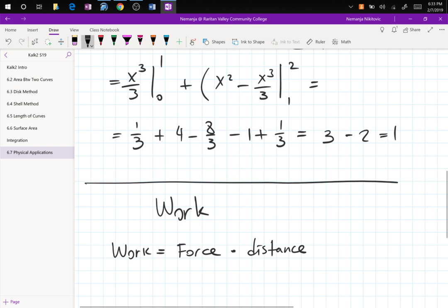So this desk is not, I mean, I'm infinitely strong, so for me it's nothing, but if you try, right? You push this way, you will start ripping the carpet. Because you are leaning onto the desk, and some of the force that you are applying is going to be trying to bury these legs that you have, and those are metal legs, right into the carpet, ripping the carpet. However, if you go like that, that was zero effort, right? Because you are parallel to the surface.